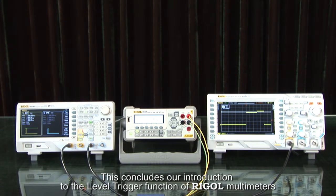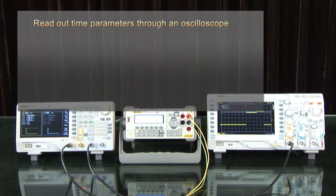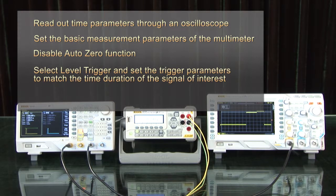This concludes our introduction to the level trigger function of Rigol multimeters. The key points are: read out the time parameters through an oscilloscope, set the basic measurement parameters of the multimeter, disable auto zero function, select the trigger level and set the trigger parameters to match the time duration of the signal of interest, and then set the integration time.